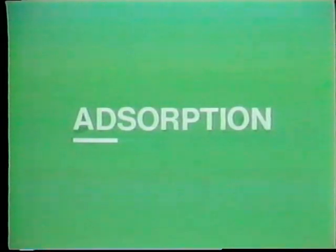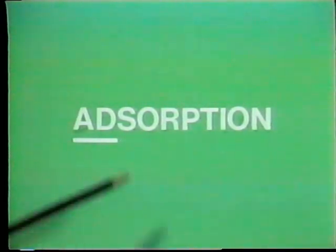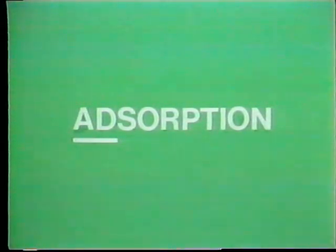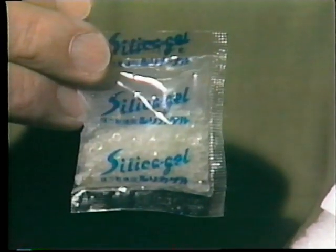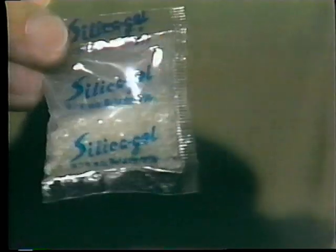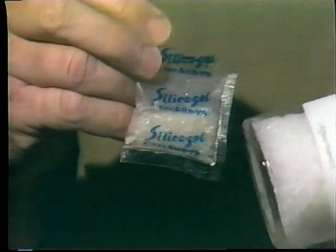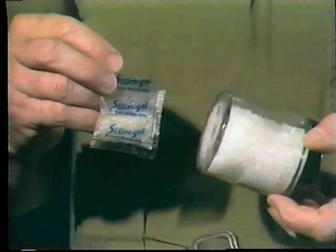The other chemical process is called adsorption, and that's adsorption, spelled A-D, not A-B. Adsorption dryers use chemicals which actually hold water vapor in small pores in the drying agent. Two of the chemicals that are being used are silica gel and activated alumina. In fact, you may have purchased a new gun or a pair of binoculars and found a bag like this inside the carton. Well, it contains silica gel, just like that used in adsorption dryers.